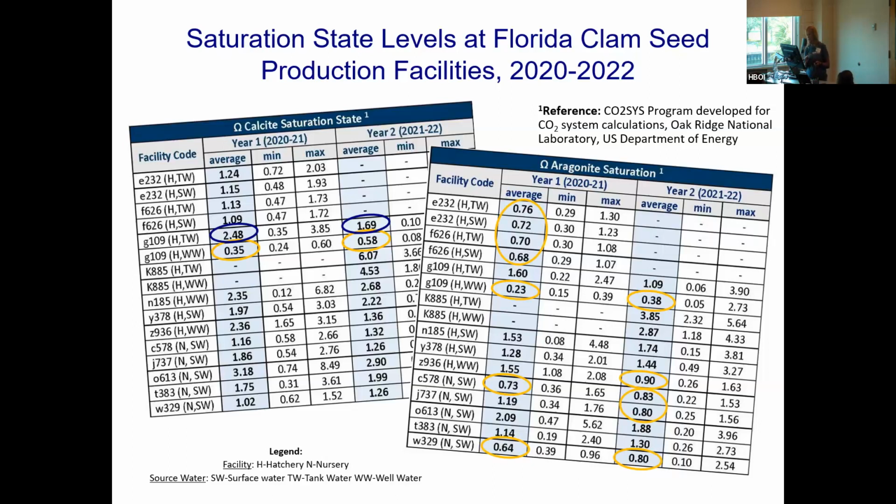But if I was a hatchery operator and I was using surface water, I think that I would take advantage of the equipment that's being provided to you, which you'll receive at the end of the workshop. And I think I would measure pH and alkalinity. If not routinely, at least spot check it. And if you cannot increase those pH or alkalinity levels to more of an acceptable range, I think that I would start aerating.